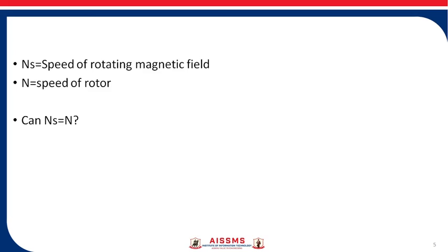So the speed of the rotating magnetic field is never equal to the speed of the rotor. The induction motor never rotates at the synchronous speed, and generally the speed of the rotor of an induction motor is less than the synchronous speed for this reason.